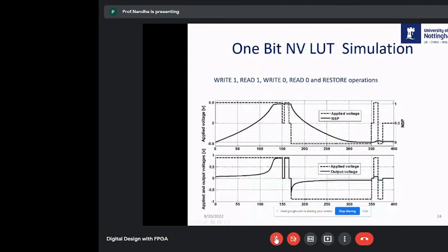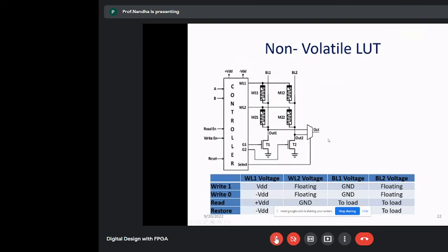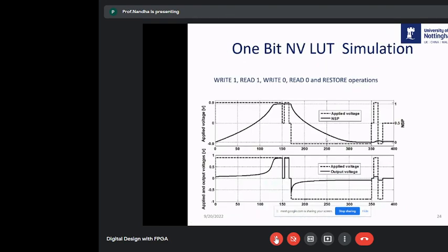When you want to write a negative value or zero value to the memristor, then you need to change from plus VDD to minus VDD. That was what I was saying here. Either provide VDD or minus VDD. So if you give a negative VDD, then you can see that the NSP goes from 1 towards 0, right? It goes to 0, and then you can see when you apply a negative voltage here, it goes to 0, and it stays there.